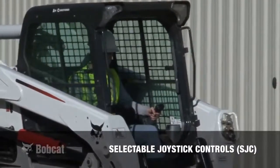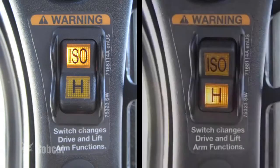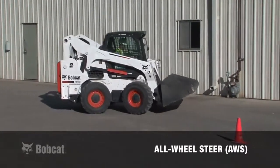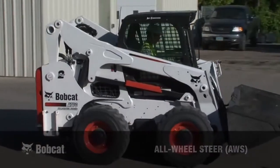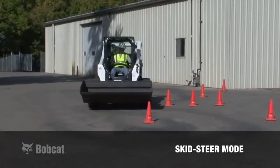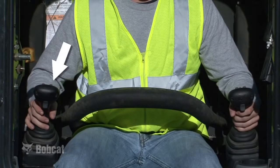Loaders equipped with selectable joystick controls, or SJC, provide joysticks to control drive, steering, lift and tilt functions. Two control patterns are available, ISO and H. The Bobcat all-wheel steer, or AWS loaders, also provide joysticks to control drive, steering, lift and tilt functions. The operator can select between two different steering modes, the all-wheel steer and the skid steer mode. Regardless of the steering mode selected, the left joystick controls drive and steering functions, while the right joystick controls lift and tilt functions.